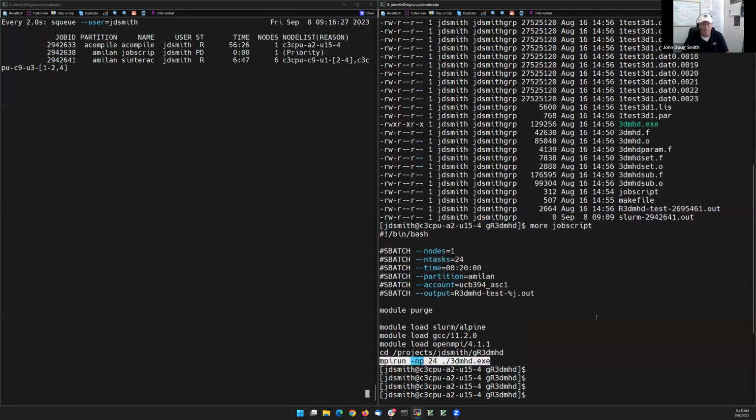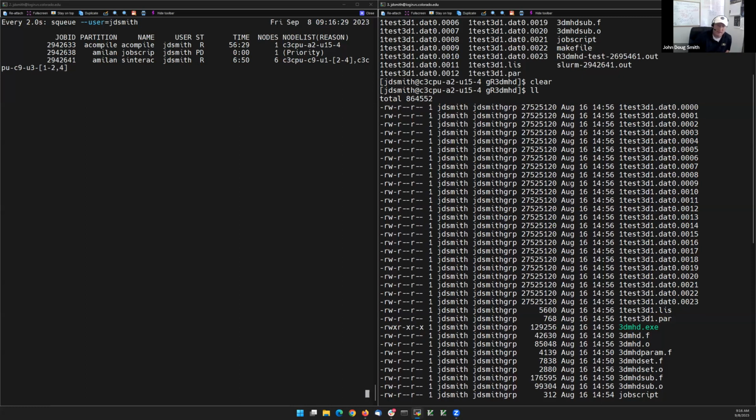Now, these files, it's dumping all of its variable information typically every iteration. So if you run a 64 process simulation, there's going to be 64 of these files. So that's why I say you've got to watch out, you may need to change how often it dumps its variables. If it's one-to-one, these files can grow very large. We will tell you in the simulation when we give it to you what things you can or can't change, right? So sometimes it's okay to change how often it dumps its variables.